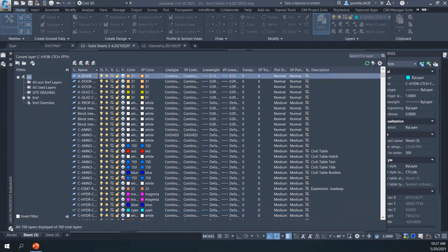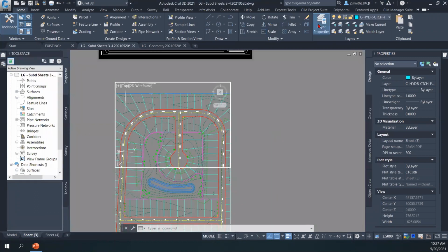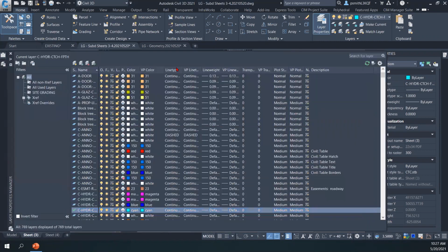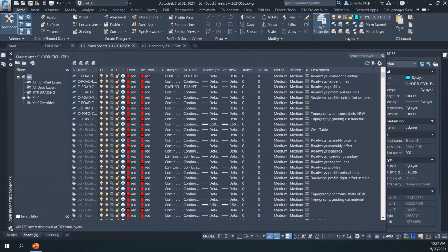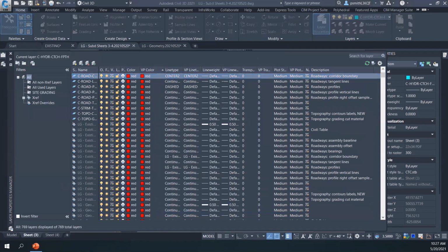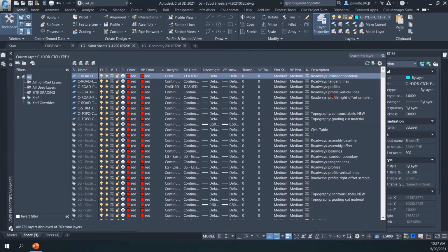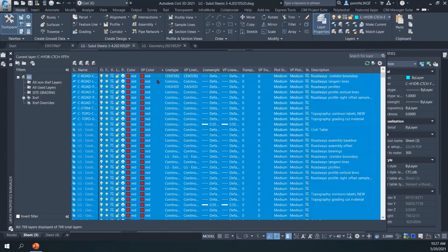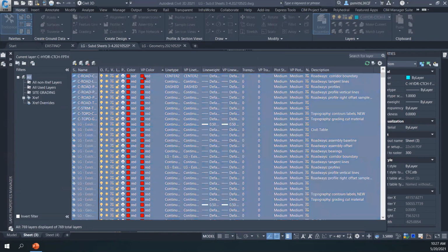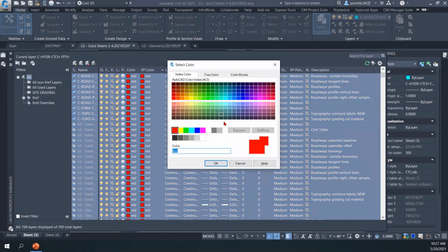And what we do here is I go back. Viewport color, select one, Control A, change that color on the viewport color tab to your screened color, which is usually probably like a 252 or 253 color.